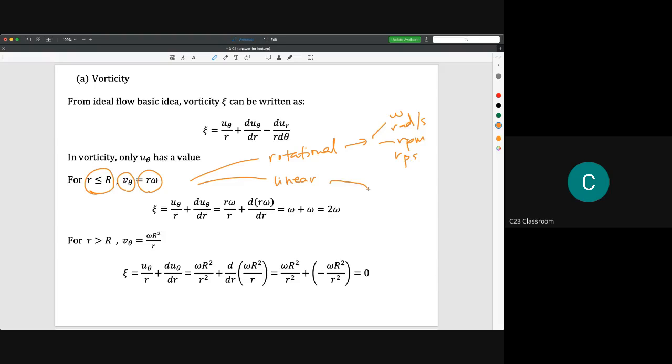However, linear speed is something where they give you units of meter per second. But sometimes you need to convert between the linear velocity and the rotational velocity, and the relationship is U equals R omega, and it is also equal to pi D N over 60.